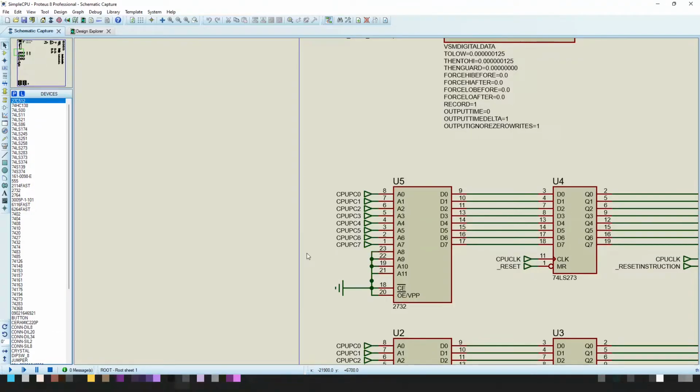The other address lines are being tied to ground, and obviously the ground is also being sent to the chip enable and the output enable. Again, the convention is that if it's got an underscore or a little horizontal line above or below the signal name, then the component will only output something if the input is driven to ground. So that's why we drive it to ground, and you're enabling the chip here. CE is chip enable, OE is output enable.